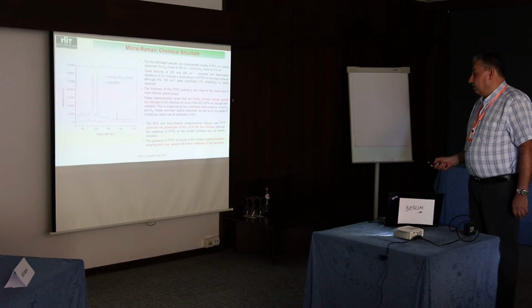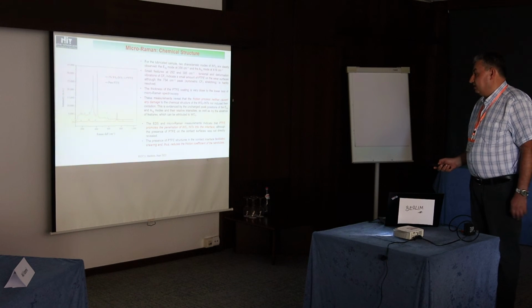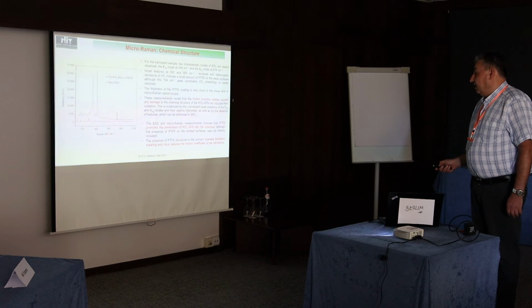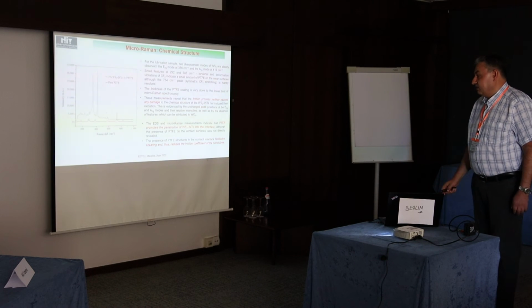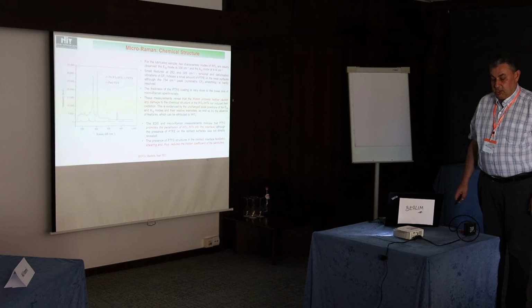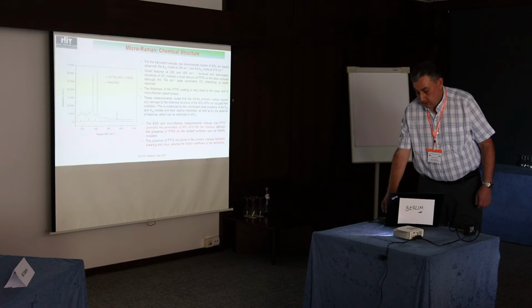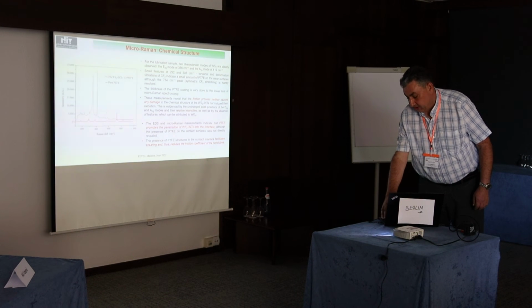though we cannot see it directly, as fluorine cannot be detected by EDS, and the Teflon layer is very thin. And this presence of PTFE structures in the contact interface facilitates shearing, and thus we suppose that it's responsible for the decrease in the friction coefficient and wear.